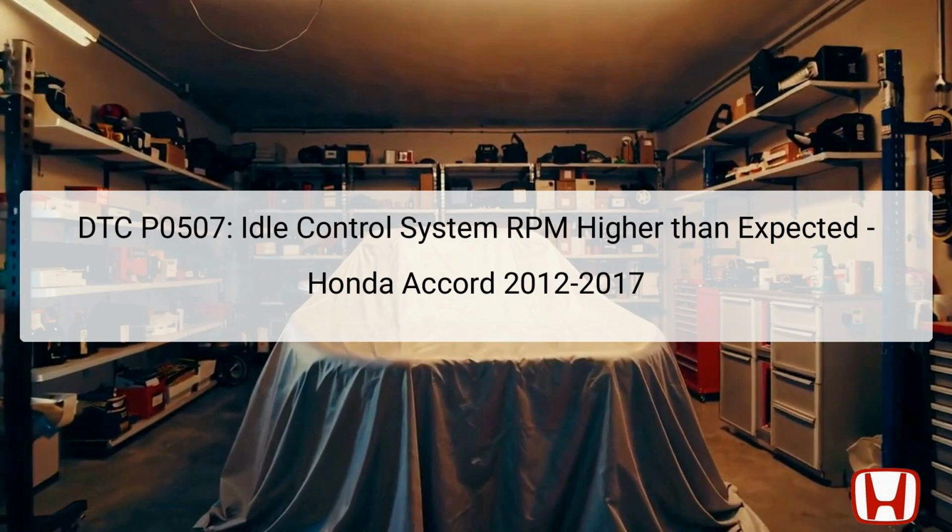The idle control system's main function is to ensure that the engine maintains a smooth and stable idle speed based on various operating conditions, such as engine temperature and air conditioning status. When the actual idle speed exceeds a set parameter defined by the Powertrain Control Module, PCM, the system flags this as a malfunction, leading to the storage of the P0507 DTC.